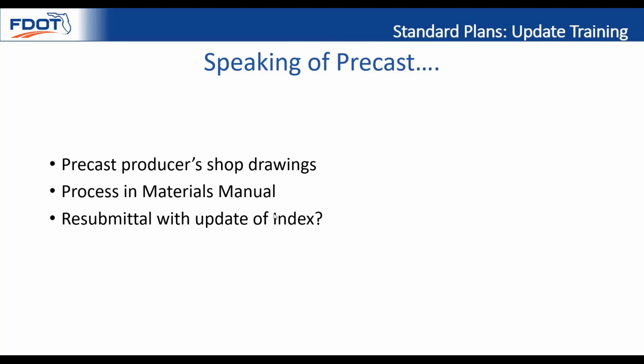Now, in the materials manual, there's a statement that the producers have to resubmit their shop drawings when the index is updated. So before folks go thinking that all the shop drawings have to be resubmitted, that's likely not the case here. The intent of resubmitting when the index is updated is in case the requirements for that index change or the actual design changes. Since this year's changes are primarily just redrawing and reorganizing, the designs themselves didn't change. The intent is not to require producers to resubmit these shop drawings.